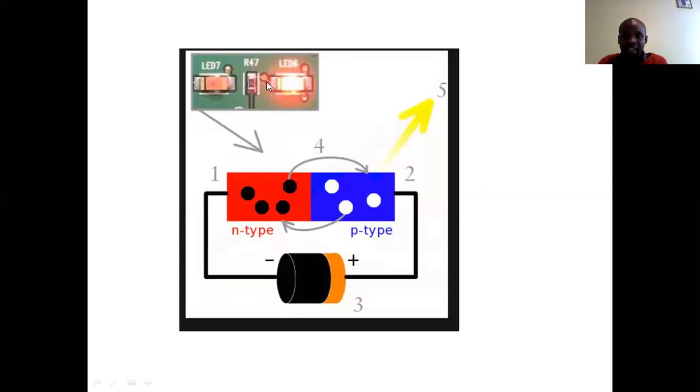This is also just an illustration. You can see our LED here producing photons. This happens due to the recombination, whereby the electrons are moving in that direction as the holes are moving in that direction. And this kind of recombination is what gives us the light. So depending on the group 3 and group 5 elements, they can give different types of light. And we have said for red light, usually it is a combination of gallium arsenide, or gallium phosphide.